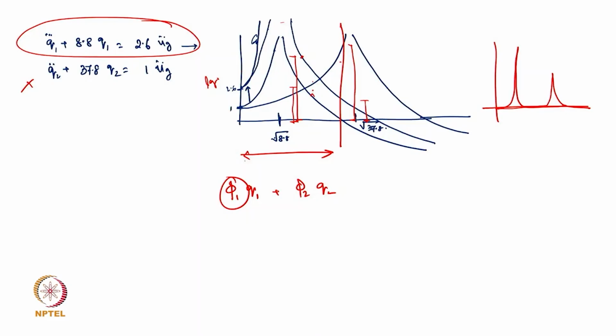Now if we go a little taller, let's say 10 storied, it will become 1 second, so your frequency will become 1 hertz. 1 second, 1 hertz, simple. If you go for the 20 storied building, it will be somewhat around 2 second time period. Frequency will be somewhat 0.5 hertz. Although these are not exact values, these are very thumb rule, but you will get it mostly closer.